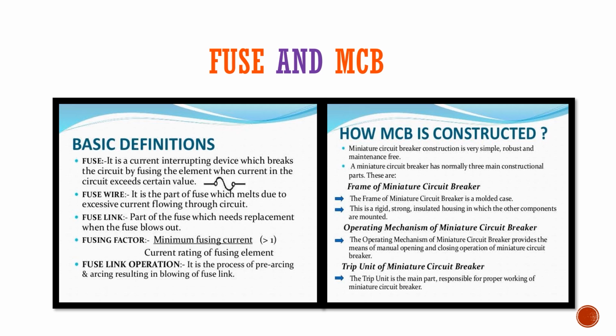Immediately you will be aware. When excessive current passes through it, a fuse is a wire of a metal with very low melting point. That means your circuit wire and the fuse wire are not the same. And the fuse wire combination is lead 75% and tin 25%. Okay, there are various types of fuse: porcelain fuse, cartridge fuse, and fuse is always connected at the beginning of the circuit. Remember that the thicker the fuse wire, the greater is the current capacity.